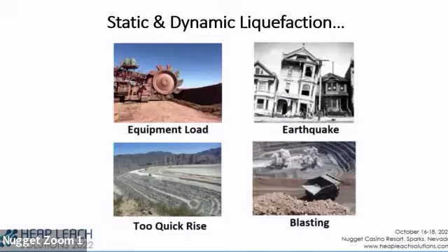Now, we're never going to have a catastrophic failure in a heap like that. The soil mechanics are identical. Our rate of rise constraints, if we have a liquefaction problem, would probably be a little more lenient because the material won't be as bad as tailings. It won't be as saturated or as fully liquefied as tailings can be. So you might be dealing with something more like 10 or 15 or 20, but there'll be a number there for static liquefaction that you'll have to pay attention to.